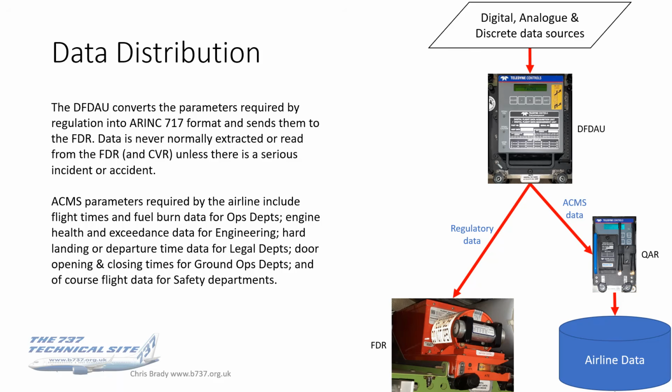Other departments that use it, well certainly where I was involved, the legal department often came to us for release of data, and you might wonder why, but sometimes you get claims in by passengers of, say, whiplash or what have you, for a claimed or alleged heavy landing. So the legal department might come to the flight data department and say, look, can you give me the touchdown G for such and such a flight, and they will then go and handle it.